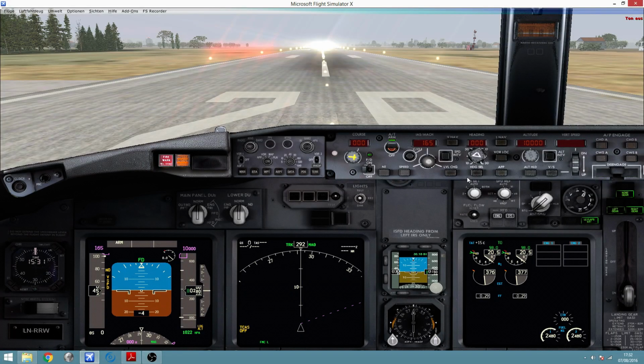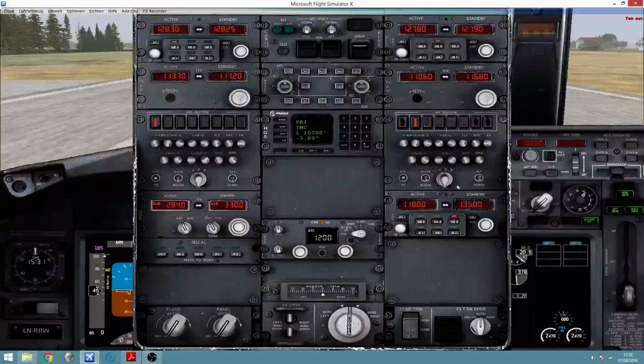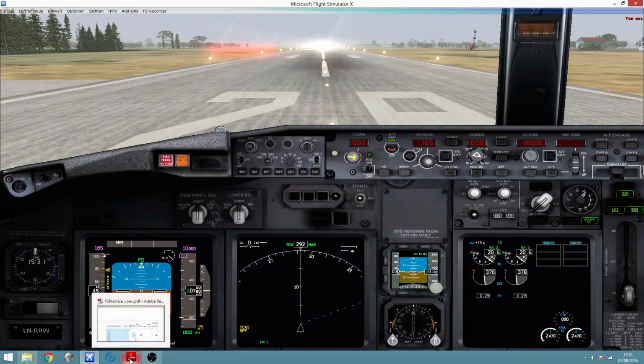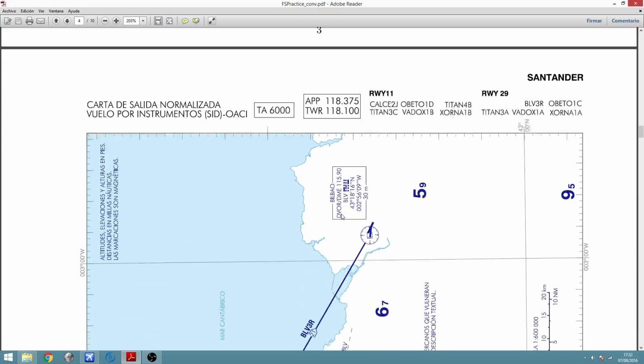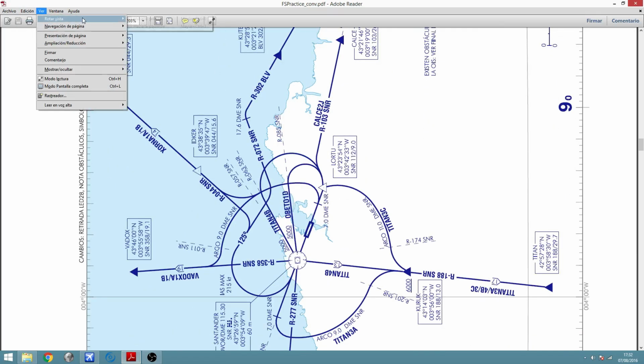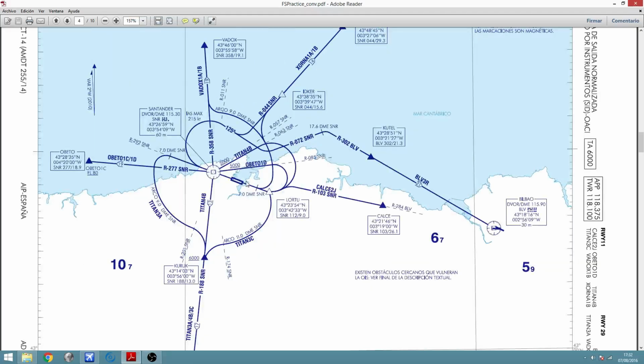So the next line says Navaids, shift 4, prepared for the standard departure, and this is where the navigation thing starts happening. The standard departure says that we have to continue on runway heading up to the VOR, and then once over the VOR, turn right on heading 125.